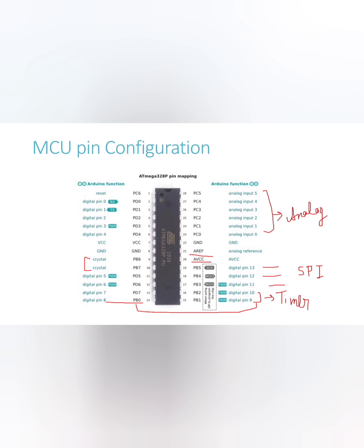In the SPI protocol, the devices are connected in a master and slave relationship in a multi-point interface. In this interface type, one device is considered the master of the bus, usually a microcontroller, and all the other devices, peripheral ICs or even other microcontrollers, are considered slaves.